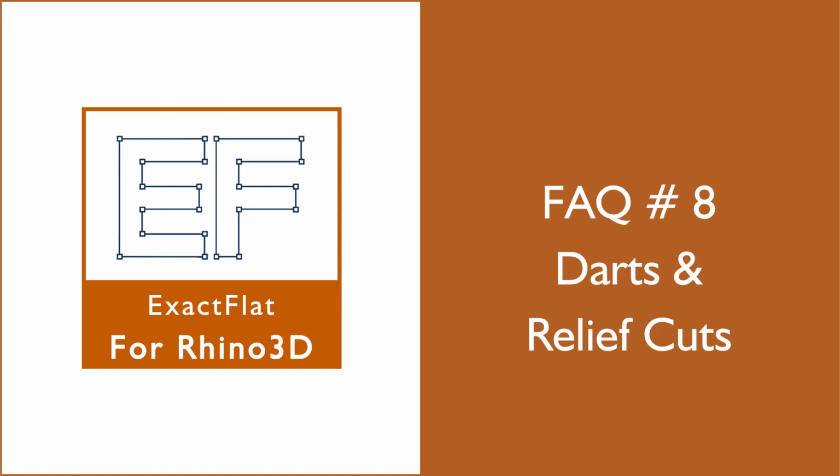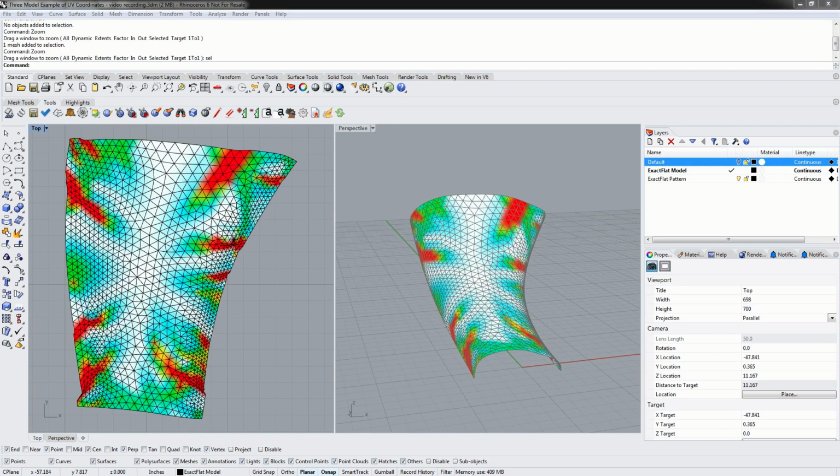Hello everyone, in this video we will talk about relief cuts and darts. Today I will show you how to use ExactFlat's shortest path cutter, the plane cutter, and the curve cutter, and I will also show you how to use some of Rhino's cutting tools to create cuts in your mesh before flattening.